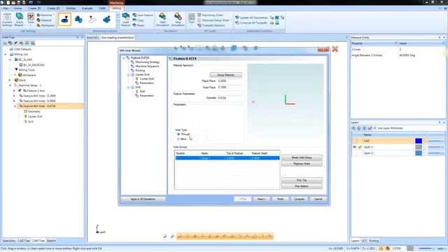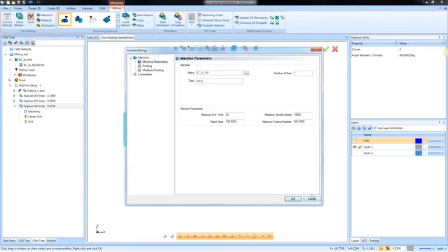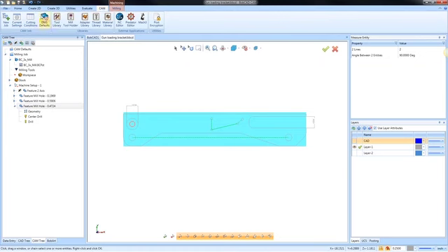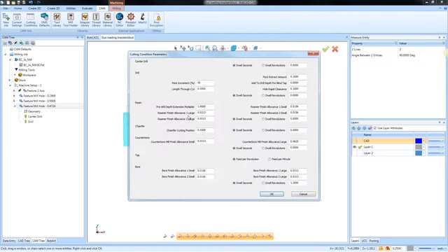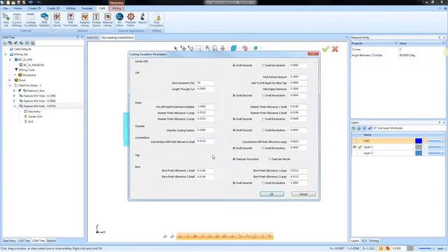Through hole, what it will do is it will punch through. It will go a little bit deeper. And if I cancel here, and I go to, let's see where this is. Let's go to, not current settings, let's go to CAM. Let's go to cutting conditions. So if we're in the CAM tab and we go to cutting conditions here, what you're going to see is some different options here. This has to do with the different drill cycles.